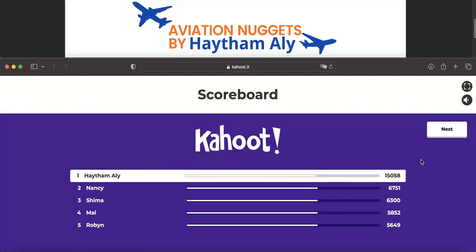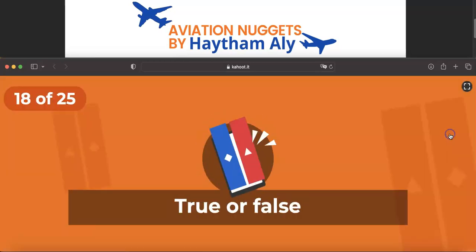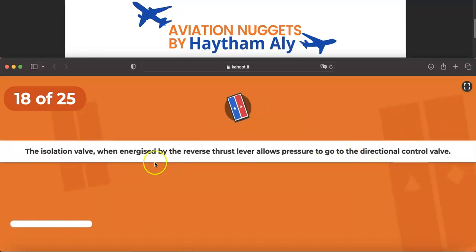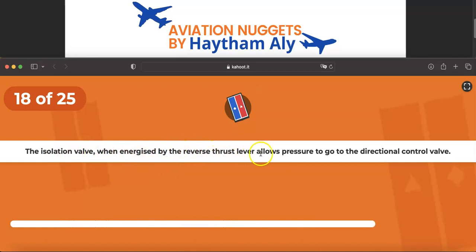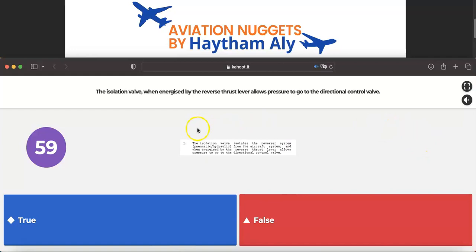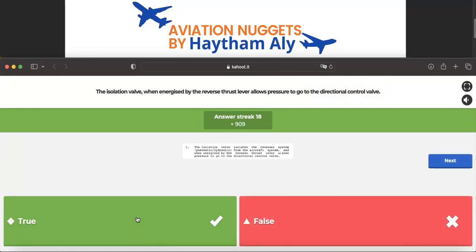I hope you enjoy these sets of questions. True or false: the isolation valve, when energized by the reverse thrust lever, allows pressure to go to the directional control valve. This statement is very true.